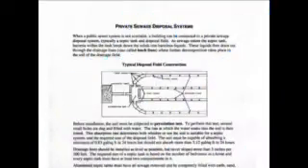And let's get on to page 33, private sewage disposal systems, or a septic system. And a septic system is installed typically in a rural area or an area where the public sewer system has not yet been extended to. Let's take a look at the diagram. Diagram's a good basic explanation of how a septic system works. Water comes into the septic tank where the solids separate and fall to the bottom. The water flows out toward the top of the tank and into the septic field.